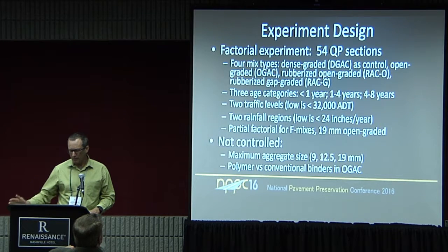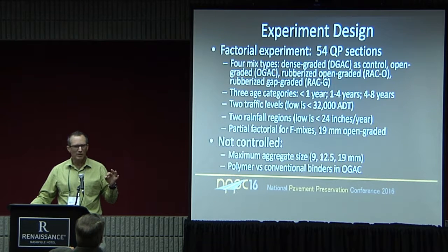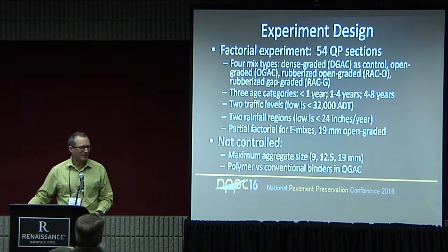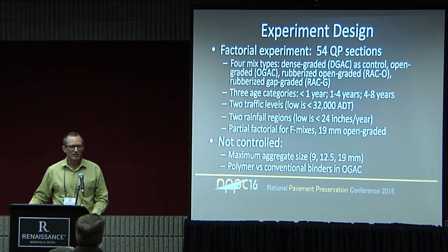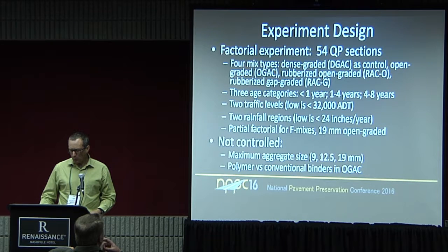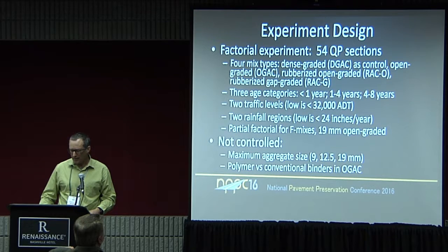Different traffic levels, different rainfalls, and we borrowed some Oregon F mixes in California for a while, where Oregon went to some very big stones in their open graded to try and get them to last longer. John Coplantz isn't here, but the general conclusion is they don't last as long, and you basically can't talk to the person next to you or even yell at them and get them to hear you because of that macro texture in those 19 millimeter, 3/4 inch open gradeds. We did not control for aggregate size, although I'll mention a couple other studies we followed up on that.